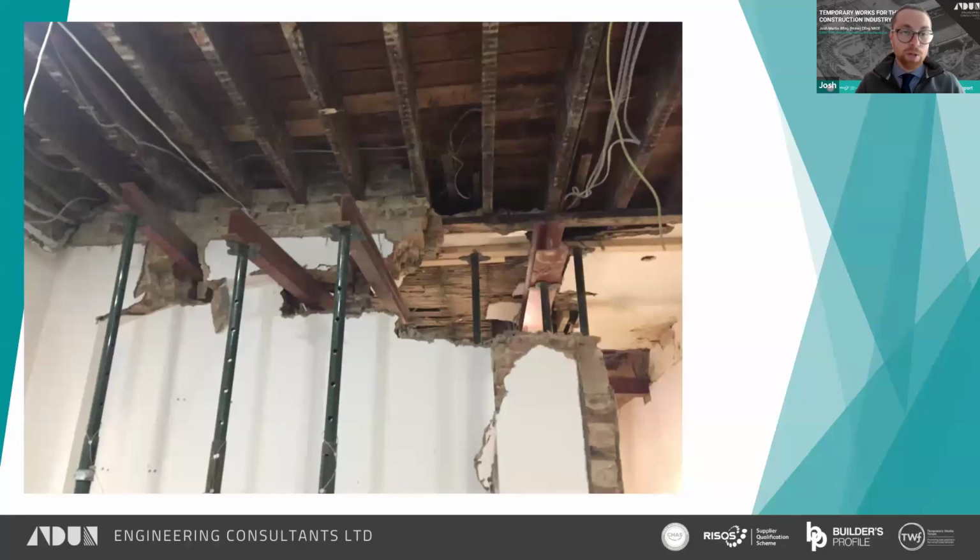There's no bracing to the props that you can see. Also, there's no positive connection between the prop heads and the lintel. We usually detail U-heads at the top of the props to make sure that they can't shift or slide off, or some positive mechanical fixings. But you can see there that that needling scheme basically isn't doing anything.